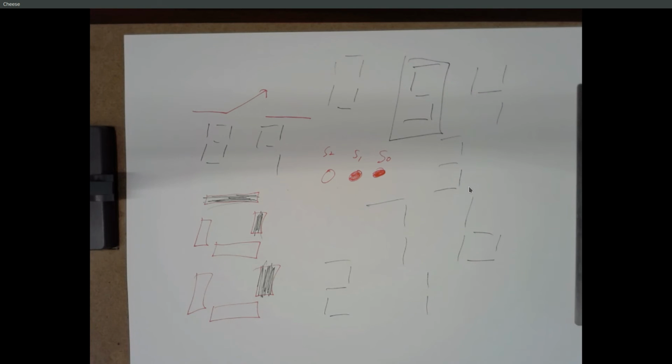And there's circuitry that we'll talk about in a week or two that does this decoding for you, so that if you feed it a binary 5, it would do whatever has to be done to make that display something that looks like a 5. That's something that already exists, and they're in your parts box. It's called the 7447. So you're not going to have to build anything extra to do that. All right, questions?